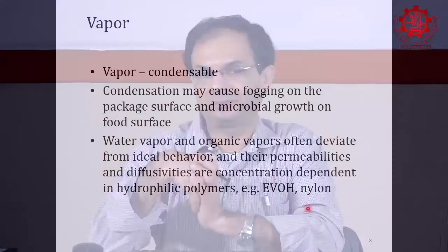Okay, so what is the sample size you take? It's significant, right? Could be 5 centimeters or 10 centimeters in diameter of film. So when you mount it on your instrument, you will be measuring permeation as well as leaks or cracks in that, and that's the overall transmission. So that's what you get, the overall transmission rate of gases or vapor, whatever setup you have.